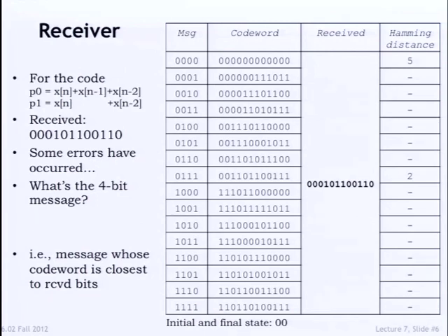So what you might imagine is, okay, you've got this received sequence. You've got a tabulation of all the possible paths through the trellis and the parity bits that are emitted along those paths. Each path corresponds to a different message. What you actually have here, let's see, we've got 12 bits here, because in addition to the message, I'm appending a 0, 0 to each one, which forces the trellis back down to the 0 state.